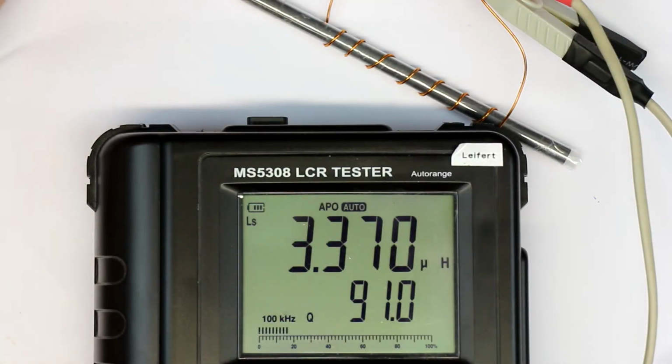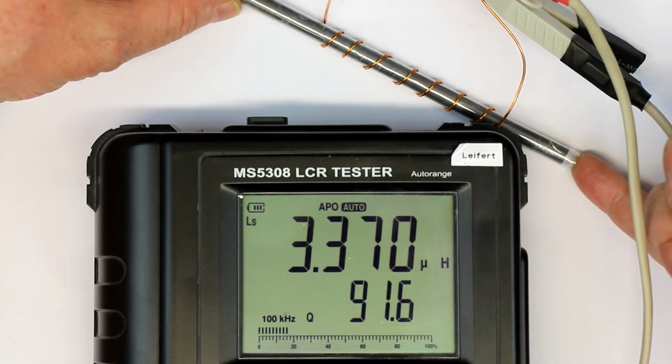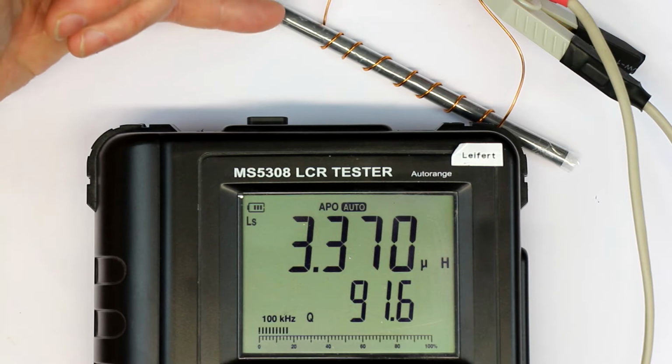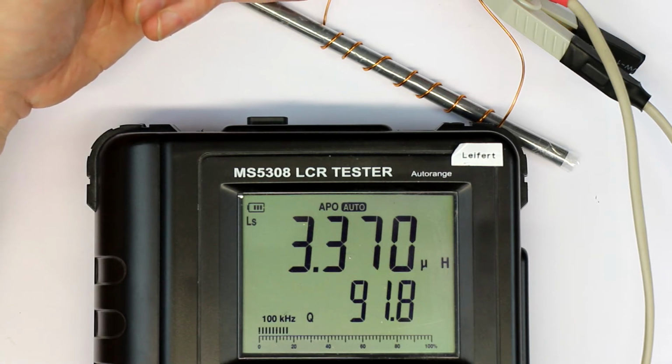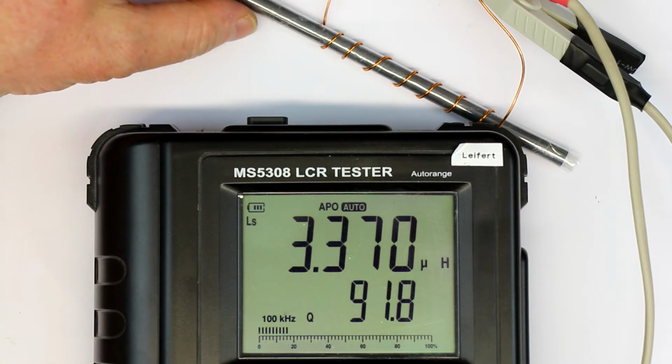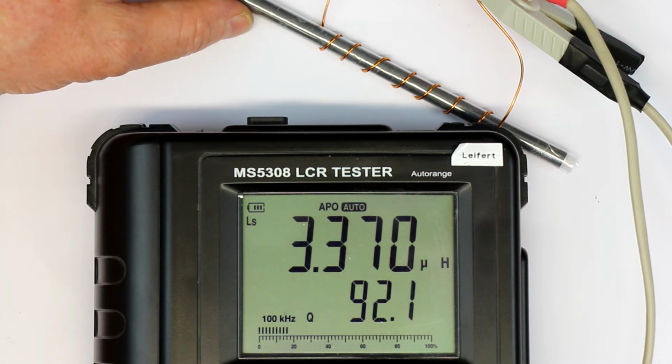You might notice some special things in this shortwave ferrite-rod antenna. First of all, you can see that there is a little plastic foil between the ferrite-rod and the winding itself. You should always have a separator and never wind directly onto the ferrite-rod.